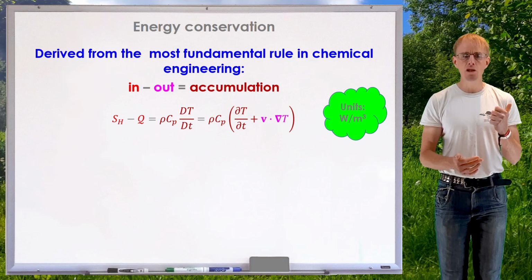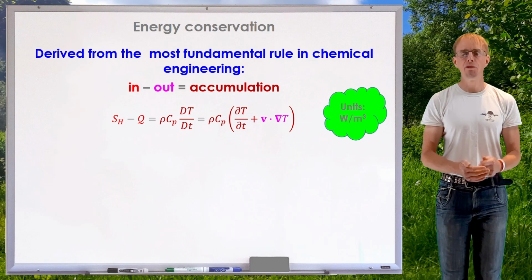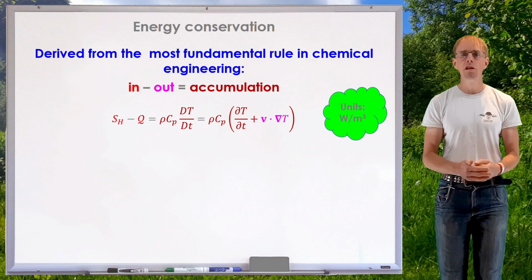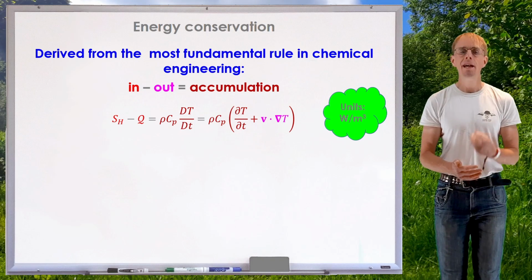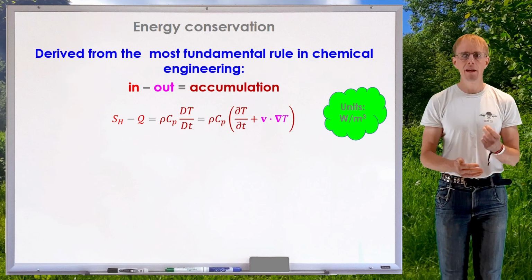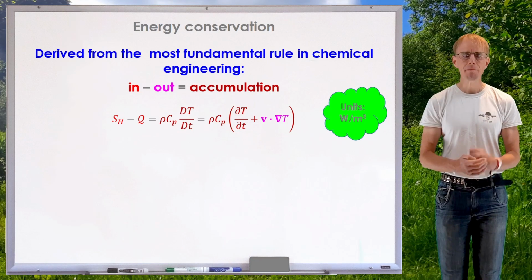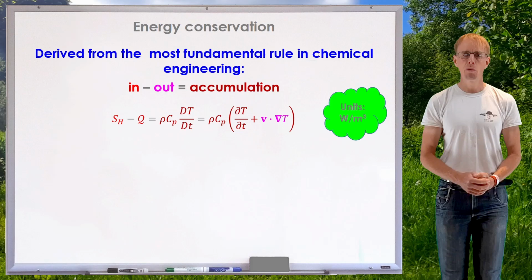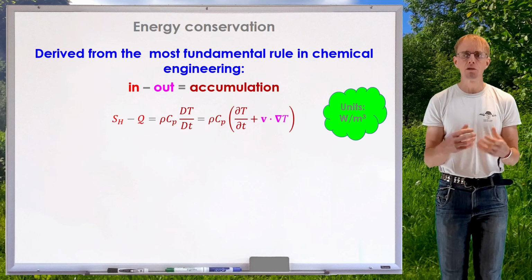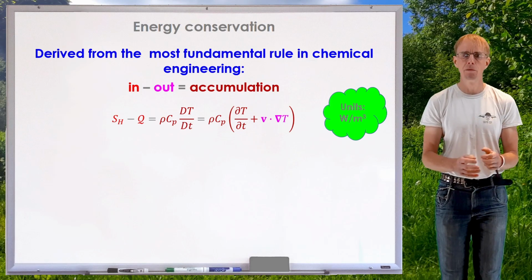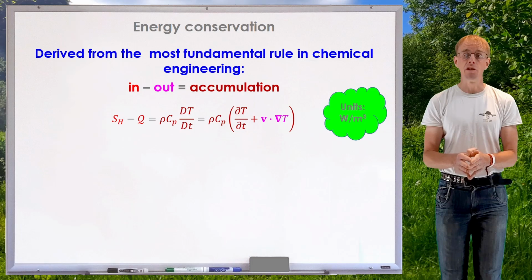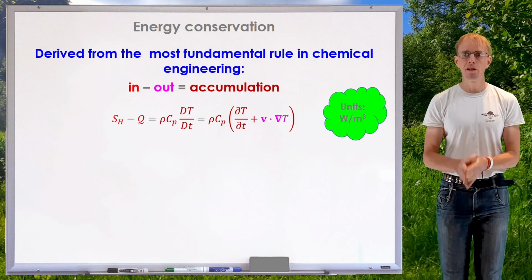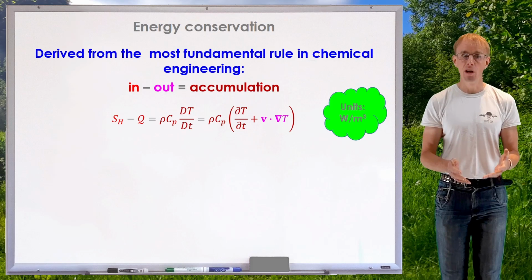And so if we look at each of these groups of terms, we find that for the energy transport equation, we're dealing with units of watts per meter cubed. It's a volumetric heat transfer equation. And this becomes very important when we manipulate the energy equation and when we flesh out these source terms, these heat flux terms, into physical processes, because we need to make sure that we're always dealing with watts per meter cubed. Otherwise, we're going to get a very wrong answer.